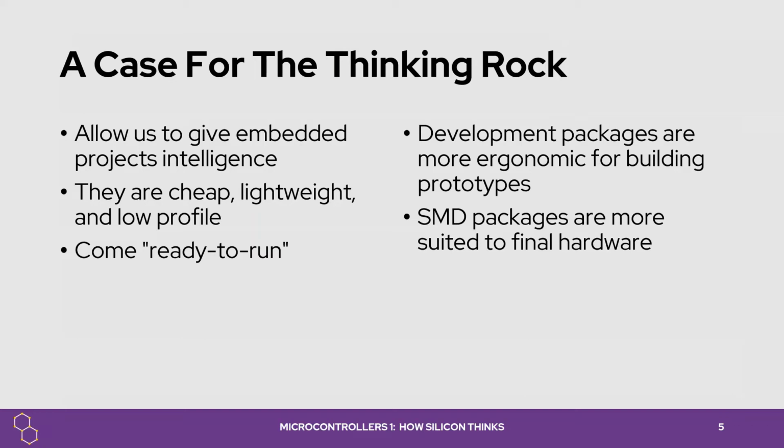For the appliances, they'd generally use the SMD components, and they'd integrate the clock and any other necessary peripherals onto the final PCB, separate from the actual microcontroller. They do that on their own. SMD components are generally cheaper because they have less silicon, they do less, and they're smaller than the dev boards. Their footprint is very, very much smaller.